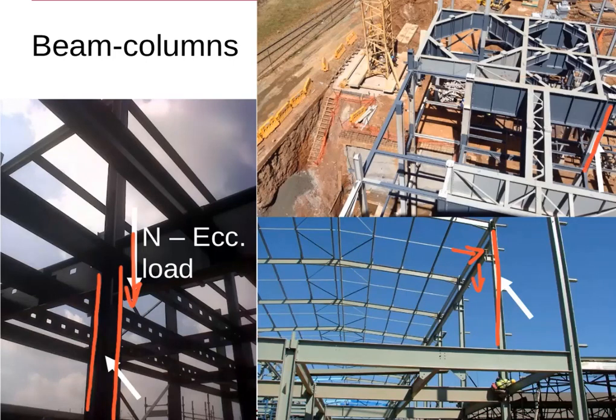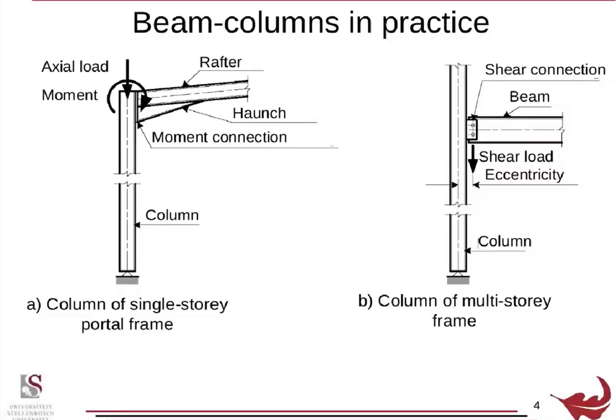For instance, top right, there you can see a column carrying very large plate girders, and then the connection causes an eccentricity in the column, so causing a moment in the column. So now here's some other examples. Here you've got a portal frame, and this is a very, very typical example of a beam column, because the portal frame is continuous, so the rafter will carry moments into the column and apply an axial load. So portal frames always are designed as beam column members.